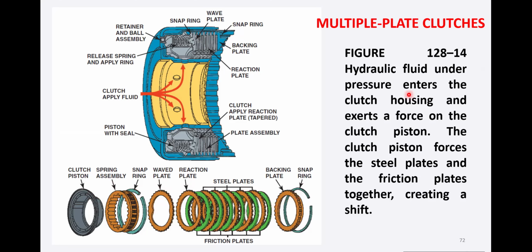So hydraulic fluid under pressure enters the clutch housing and exerts a force on the clutch piston. So it is exerting the force on the clutch piston here. The clutch piston forces the steel plates and the friction plates together, creating a shift here, and it's locked here.